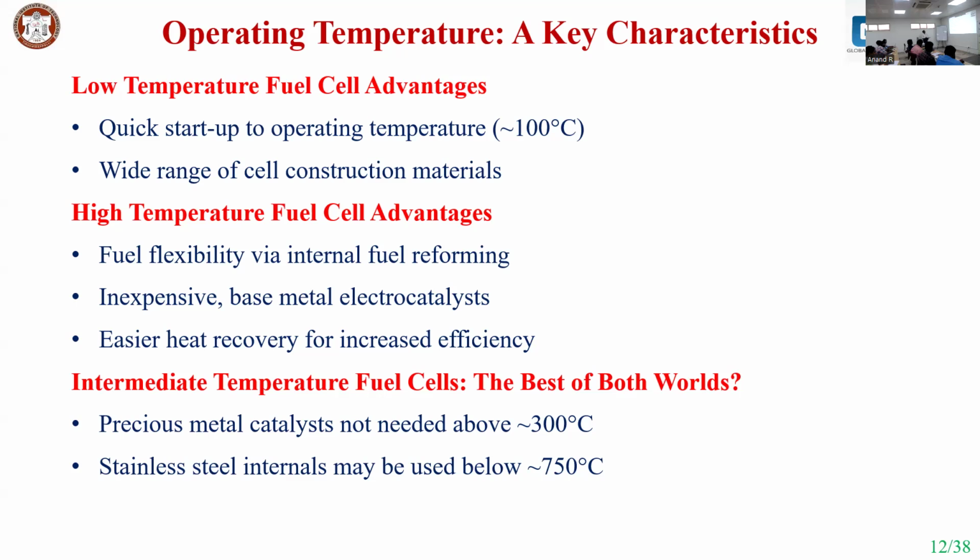So all hydrocarbon or alcohol based fuels can be utilized for high temperature fuel cells. But from the environmental and economic perspectives, a lot of research is needed to take care of the emissions as well as the economics. Because as the temperature increases, the cost of the fuels will also increase. At high temperature, precious materials can be utilized for the fuel cell or electrode coating, so it will increase the cost.